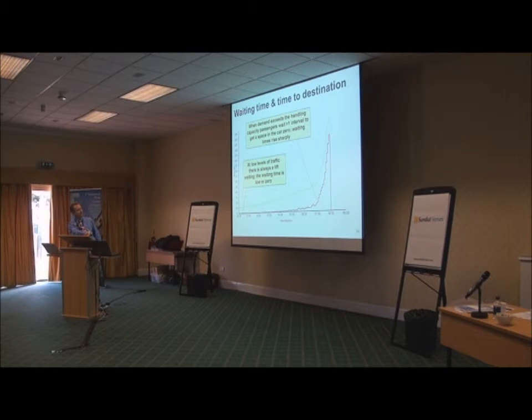At the sort of 14% demand level, it all works beautifully, and it's a 60% relationship, and everything is good with the world. And then we end up with more traffic, and the queues get longer and longer, and people have to wait more and more intervals until they can get into the car, and then the whole thing saturates and falls over. And that's why in all the guidance where you extrapolate waiting time from interval, it says check it with simulation. It's complicated. If you can get a reliable equation to do this relationship, then that's brilliant. I'm looking forward to it, but I haven't found one yet, and therefore if I'm going to check it with simulation, I'll start with simulation. It's easier.